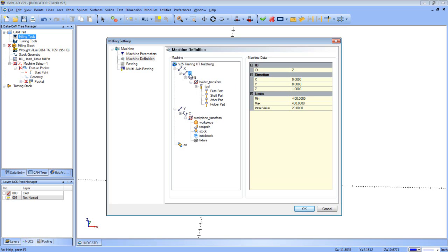Now the Z is again the tool moving, so we're going to do a positive 1 in the Z. And for this one we're just going to use travels of minus 15 from the 0 and positive 20. So it can go up 20 inches from the spindle face on the table, and it can go down an extra 15 when it's rotated around on its side. Now my initial value is okay because it's in between those two numbers. I'm just going to center it more a little bit and bring it to 0.